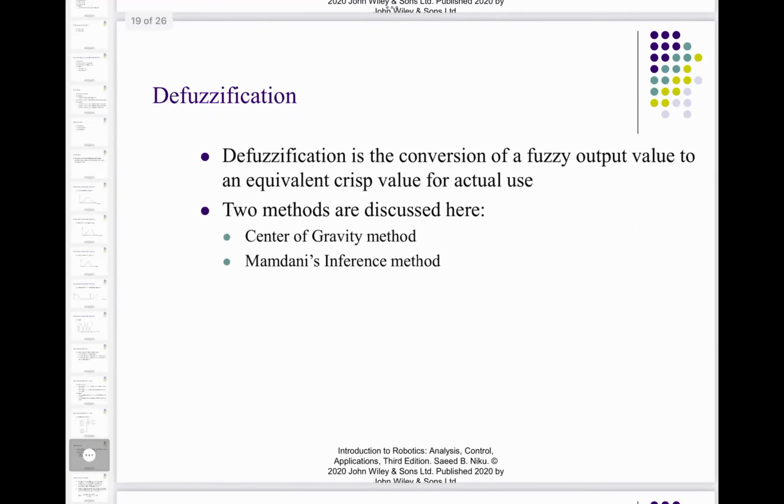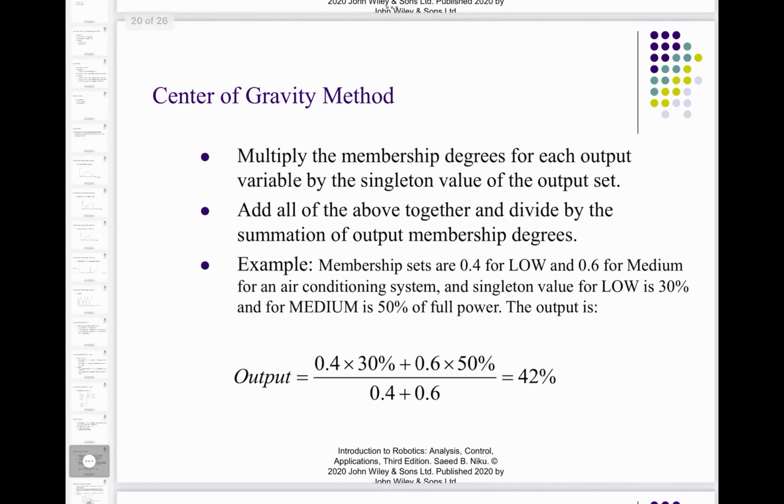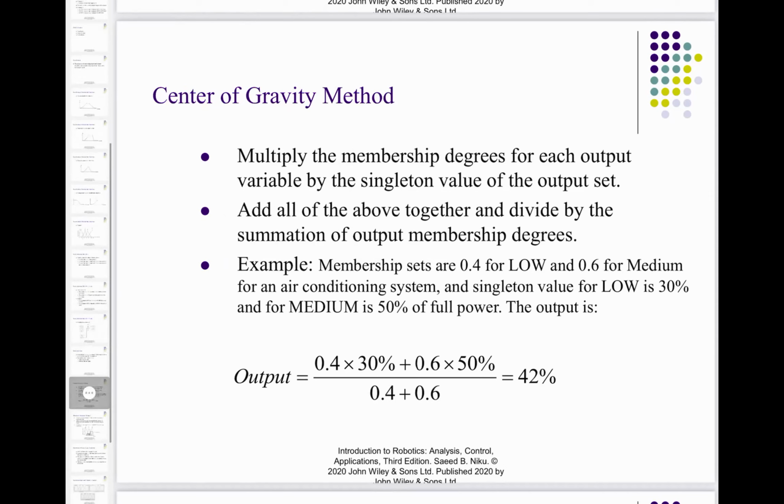And then you basically do a defuzzification, which means you get the output from the inference system, and that output from the inference system is mapped to the crisp result. There are two techniques that are used, and I talked about these techniques briefly in last class. One classic technique is the center of gravity method, which means you look at the weights, multiply those by the membership functions, add those and find where the centroid is. So where is it mostly located?